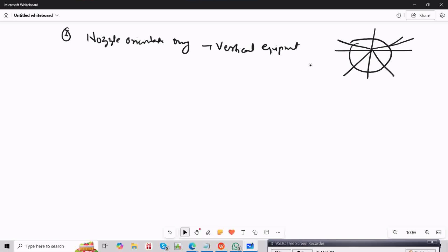Now the seventh point is called the vessel cleat location drawing. Now, what is vessel cleat location? Because of this nozzle at an angle, the pipe connecting to it is also at an angle, and this pipe has a support from the column surface.